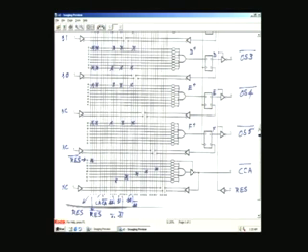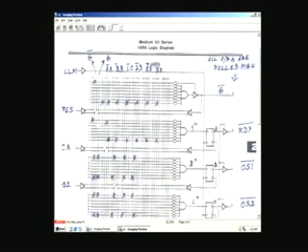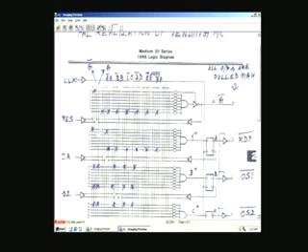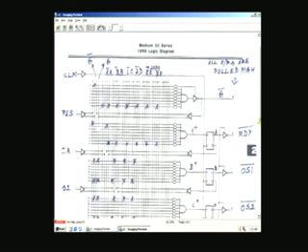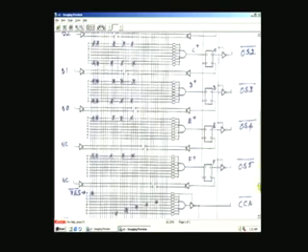And then the one final here, you have this G bar, which is not an output or input, but G bar is an intermediate term. Since we did not write the individual equations for the A plus, B plus, C plus, etc., if you write them, there will be a combination which is common to all of these. That term we call G bar, and that we are realizing, and this combination is applicable to all the inputs. So G bar is taken as the input to all the other registered outputs. So this is how we implement it.